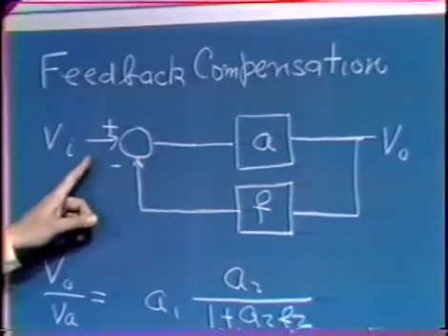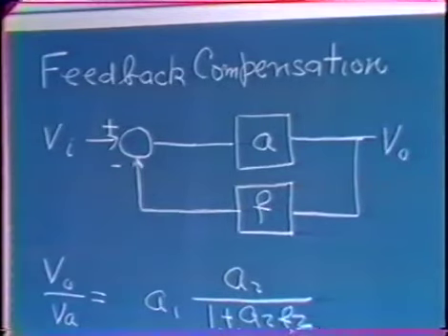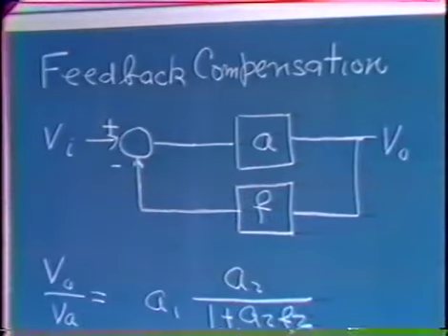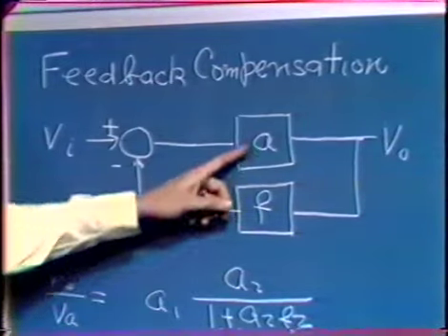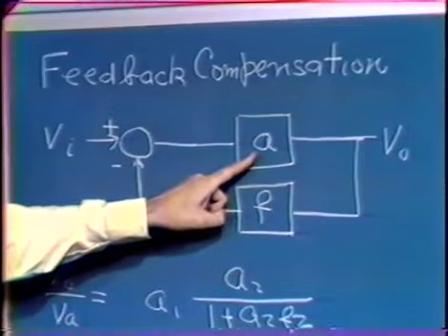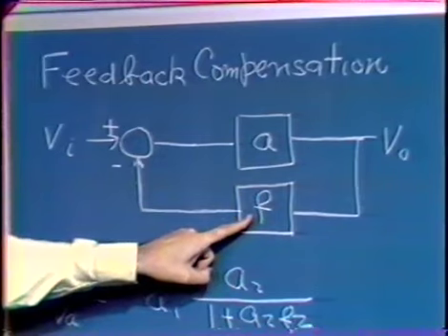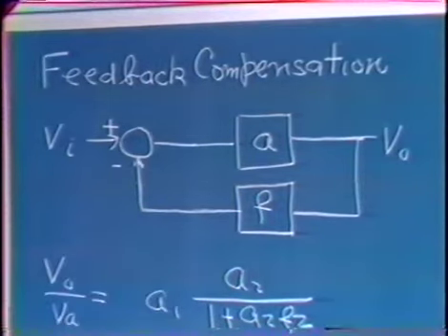And for that we have our general feedback form, the kind of feedback system form we've been considering to this point, where we have a forward path A and a feedback path F. Very frequently the physical situation constrains the transfer functions of these two elements. We frequently consider the element A a fixed element. F is very, very frequently constrained by the ideal closed-loop gain for our configuration.